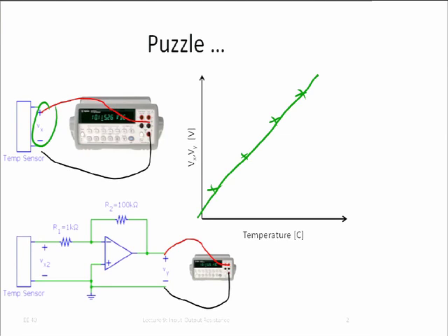So then I said, well, gee, that's no problem. We learned about amplifiers in EE40, so I applied one on the circuit, and I use this down here, right? I have the temperature sensor, I have this amplifier stage. Is it inverting or non-inverting? It's inverting, right? It's an inverting amplifier. What's the gain? Is it 100? Minus 100. Okay, so the gain is minus 100 because it's an inverting amplifier.